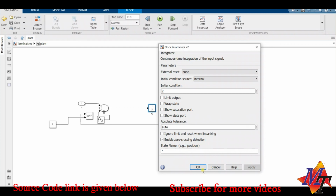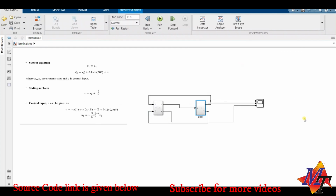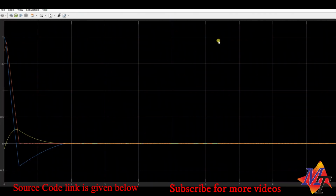Because we have not defined the initial system state, the initial conditions. For x2 we take it as, suppose, 2, and for x1 we take it as minus 0.1. So when we run it now, and we see the output, we can see the output here, that is all system states, firstly blue and yellow are the system states, and they reach 0, the equilibrium point, in very little time, less than 2 seconds only. And for the sliding surface we can see this is the reaching phase and this is the sliding phase. So this is how this control scheme works for a non-linear second order type of system.